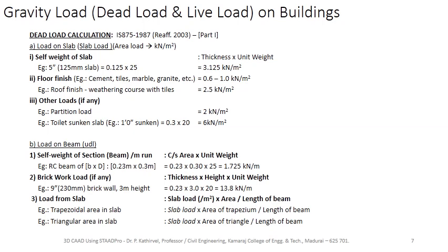So summing up all these three, you get the load on the beam as UDL. Examples have been shown for self-weight of beam, brickwork load, and load from slab. From this, the dead load on slab and beam are calculated, which are to be fed into the software.